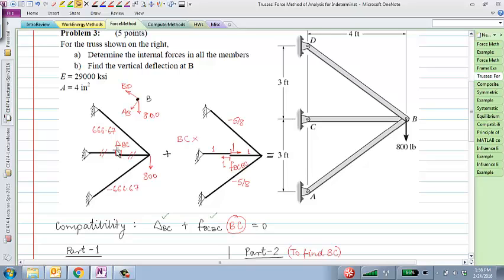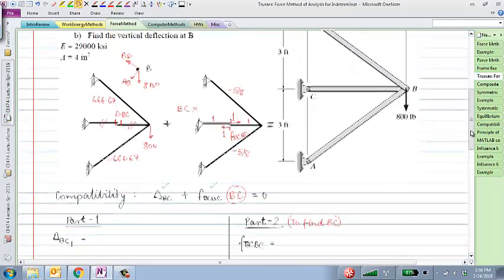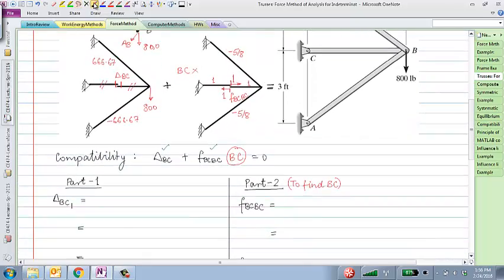Since I want displacements at that point, I'll apply P prime and minus P prime at that point, which again at the end will cancel off. So I'm just applying 1. According to the virtual work method, I will have virtual internal forces, small n, and I'm going to write that as n prime as well because it's virtual forces, times the real displacement of each one of those members.